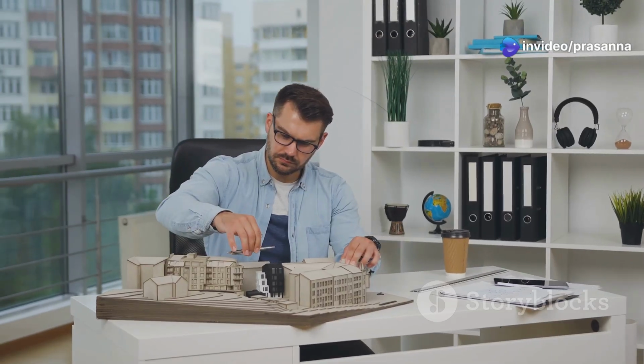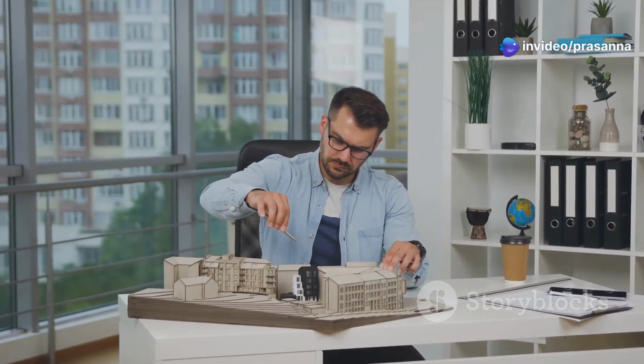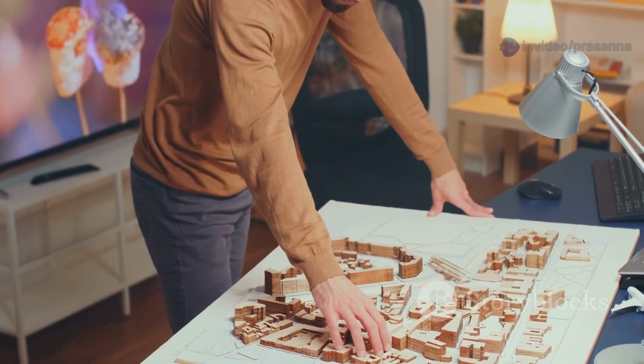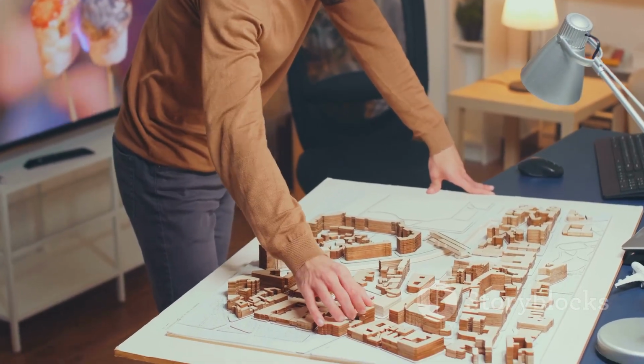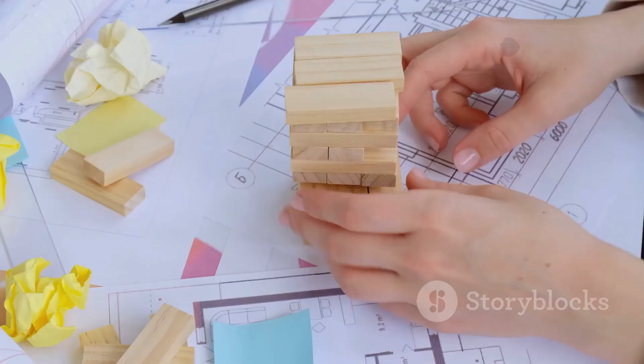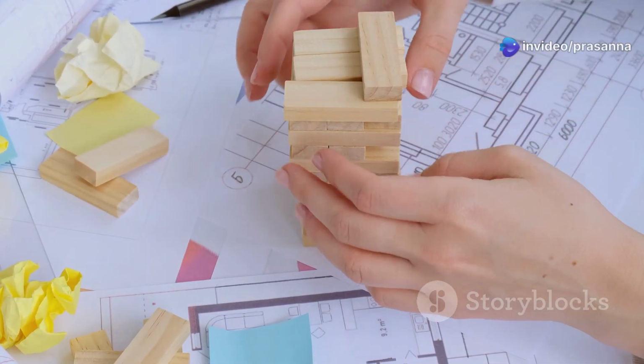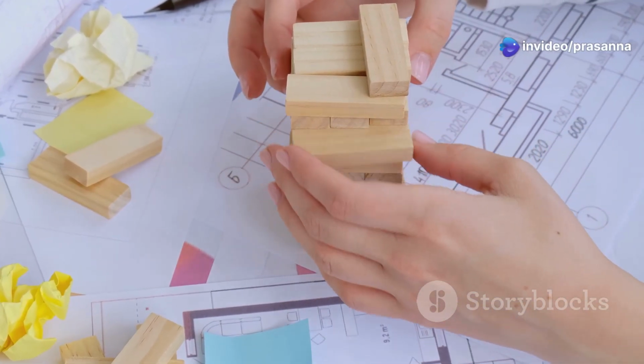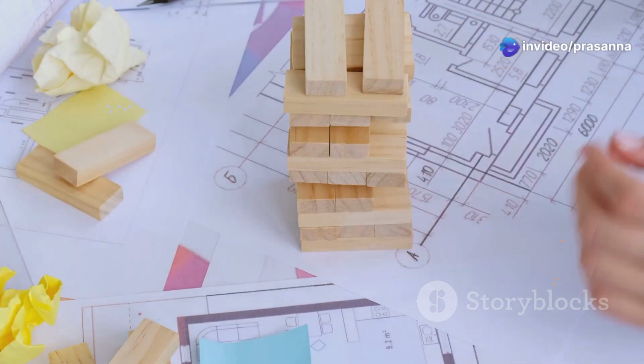For example, you might hide the roof layer to work on the interior, or you might hide the furniture layer to see the room layout more clearly. Always assign groups and components to specific layers. Do not draw raw geometry, like lines and faces, directly on different layers other than layer 0.